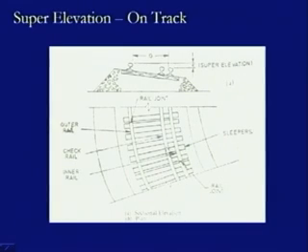as check rail. We have discussed the check rail before also, and what we have discussed is that because of the centrifugal force, there is a tendency that the hull of the system will move in this outward direction, from this side to this side. Once we have provided this check rail, it will not allow the wheels to move further in this direction, it will restrict that movement. And this is how it checks the movement in the lateral direction of the rolling stock because of certain reasons like the centrifugal force in the case of a curve.